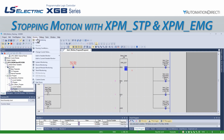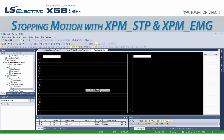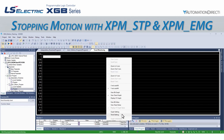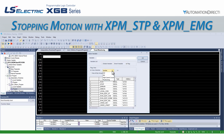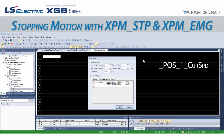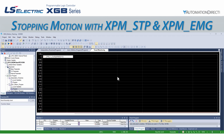We go to Monitor, Trend Monitoring, right-click on the screen and uncheck View Bit Graph and Display XY Graph, and then right-click and select Trend Setting to add our desired variable. In this case, we will add the system flag variable pos1 cur speed to the trend graph. This will allow us to see the speed of the axis and how it relates to these two stopping functions. Since we are in monitor mode, the trend is already running.